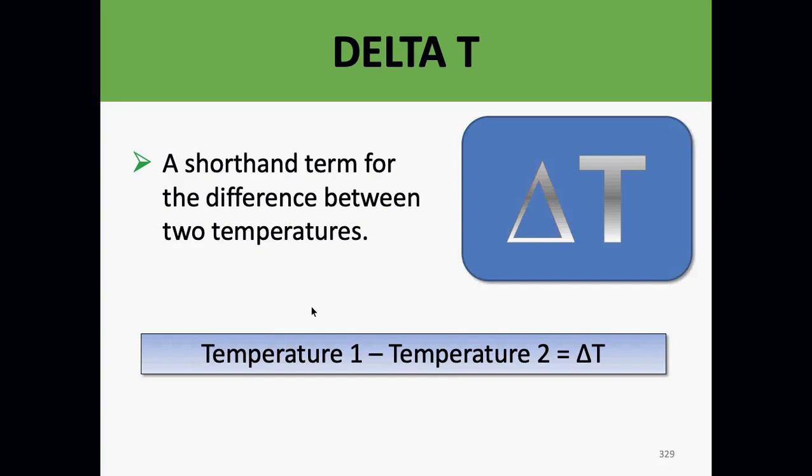But when you put it into a formula, unless it specifically says to use that negative, just drop the sign, use the absolute value. Okay? So again, you can end up with negative delta T's. It happens in air conditioning all the time. But drop the sign and just use the absolute value.